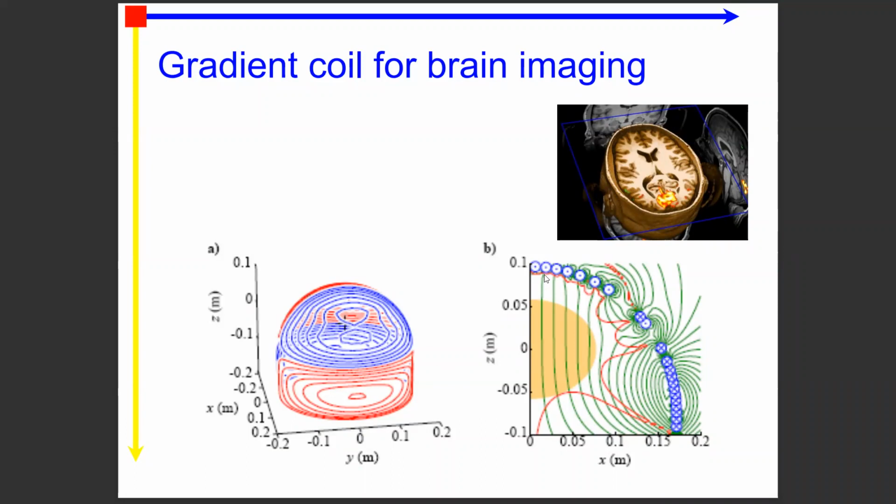And you can see here how it's optimized, let's say in MATLAB or it could be Python. You can actually design it to have a uniform region. This red region here denotes the uniformity section of that space. This is a cross-section of a three-dimensional volume. These are the loops which are carrying the current out of the plane and into the plane as X, right? And these are just fringe fields. Fringe fields leak outside. We want to minimize those so they don't reach the superconductors.